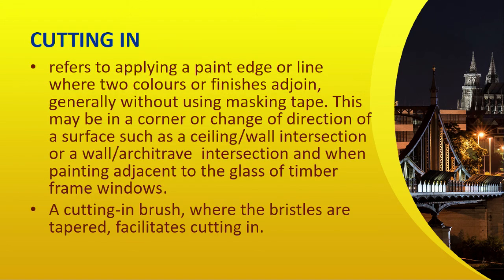Cutting in refers to applying a paint edge or line where two colors or finishes are joined, generally without using a masking tape. This may be in a corner or change of direction of a surface, such as a ceiling or wall intersection, or a wall or architrave intersection, and when painting adjacent to the glass of timber frame windows. A cutting in brush where the bristles are tapered facilitates cutting in.